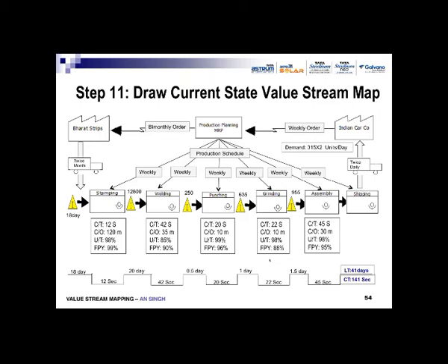It shows that the total lead time for production is 41 days, whereas the processing time or cycle time is just 141 seconds. This reveals the actual condition of operation. The material is hardly in contact with the various processes for less than 3 minutes, but the total time spent by the material from the entry gate to the dispatch or shipping gate is 41 days.